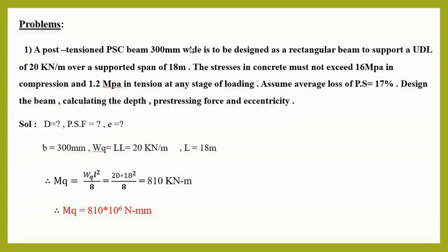Here it's a post-tension PSC beam having a width of 300 mm. About the depth, they have not mentioned. We should design the depth. So they have clearly mentioned it's a design problem. And simply supported beam carrying a UDL of 20 kN per meter and length of it is 18 meter.